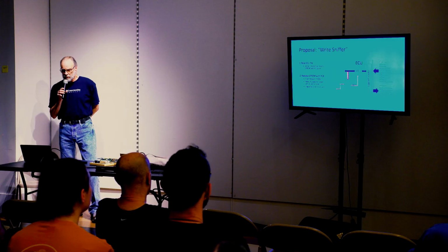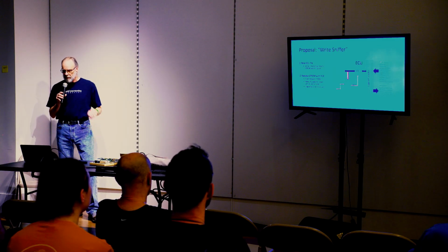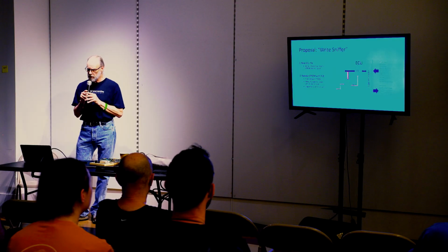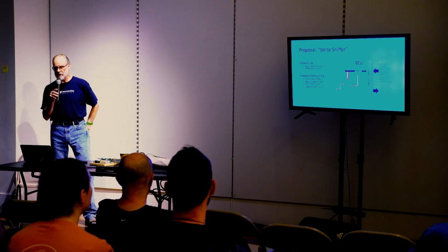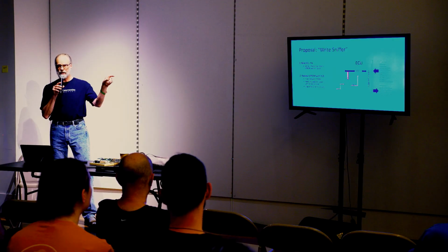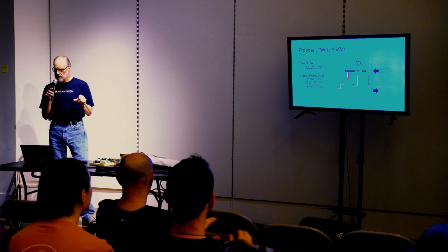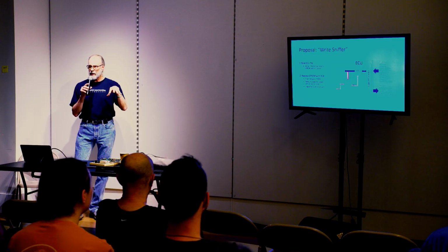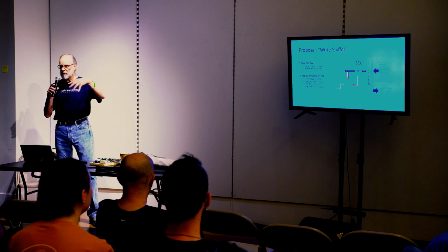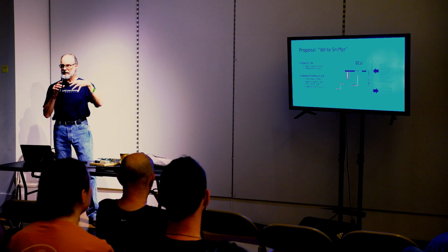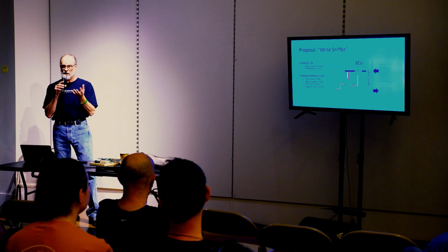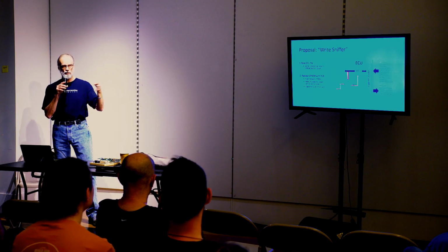So what I came up with, I called the write sniffer. And what I was going to do was modify the ECU firmware so that whenever it calculated something interesting, it would write that interesting thing to the EPROM address space. Then I would take a circuit board, plug it in place of the EPROM, and it would have all of its GPIOs basically connected to that EPROM, so that it could detect the write cycle. And every time it saw a write cycle, it would just grab everything off the bus and log it.